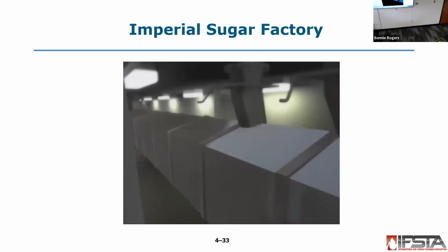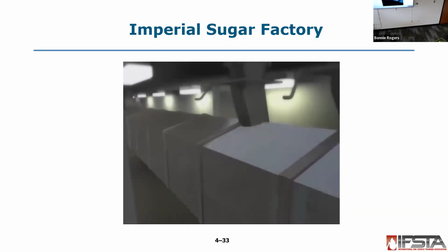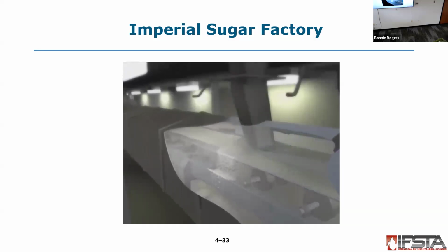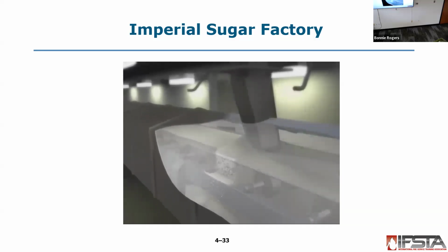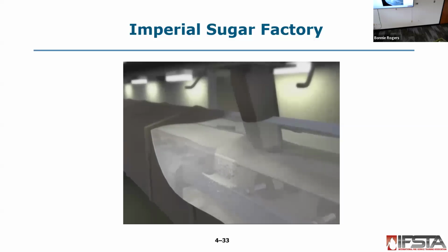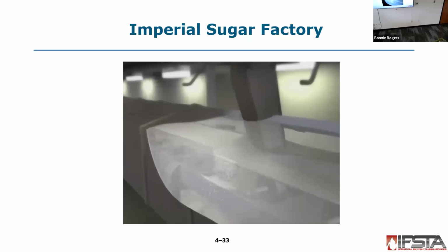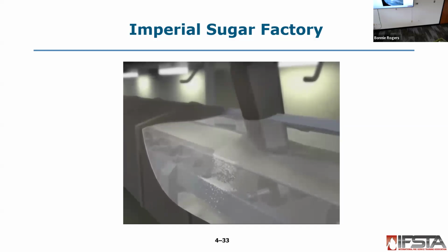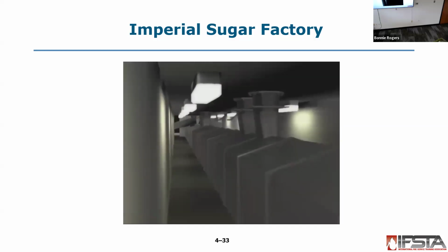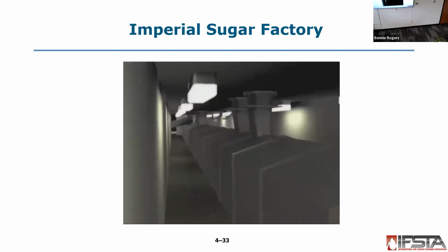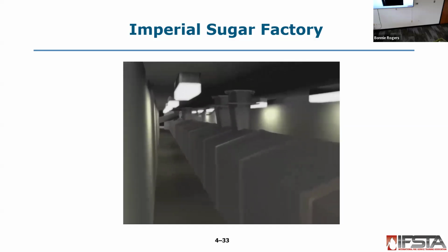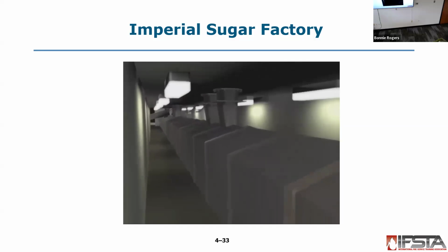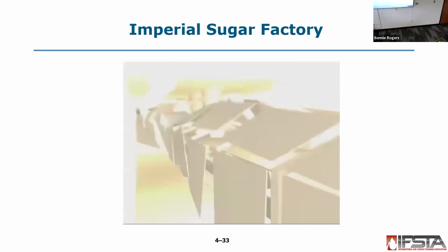On February 7th, 2008, clumps of sugar were found blocking one of the discharge chutes. Sugar from the adjacent silo likely spilled off the moving belt. Dust likely accumulated to an explosive concentration inside the enclosure. At about 7:15 p.m., the sugar dust contacted a nearby ignition source, likely an overheated bearing, and exploded.